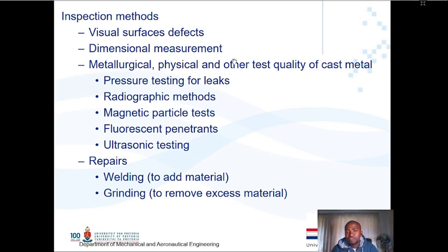Pressure testing will be one of them. Pressure testing is a process mostly found in pressurized vessels. You want to pressure test your vessels before you deploy them into operation. So you take your pressure vessel and expose it to pressure and see if it leaks. If it doesn't leak, then you're good. There are no leaks.